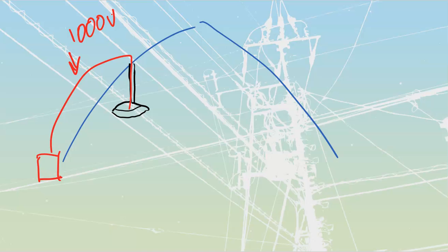They do talk a little bit in this section over here about merc vape and metal halide, because that's a common thing that we are going to remotely mount. Less common with standard fluorescent. But some of those, the merc vape and the metal halide, don't have a high striking voltage, whereas this other one we're going to learn about, the high pressure sodium, not the low pressure one that we looked at, but the high pressure sodium, is going to have a ridiculously high value of voltage, and so it needs specialized conductors because it also gets more voltage drop.